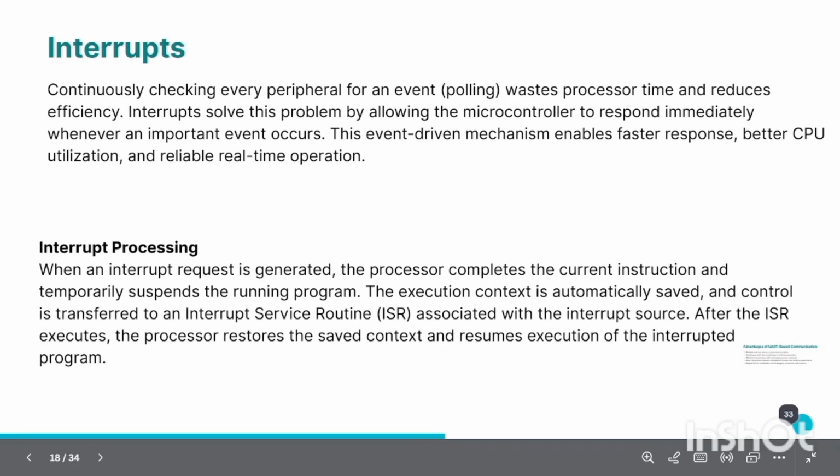Event driven interrupt processing. Continuous register polling wastes processor cycles. Interrupts resolve this by shifting the system to an event driven model. When an interrupt triggers, the CPU pauses the main thread, context switches to the designated interrupt service routine to update system flags, and immediately resumes normal operation.